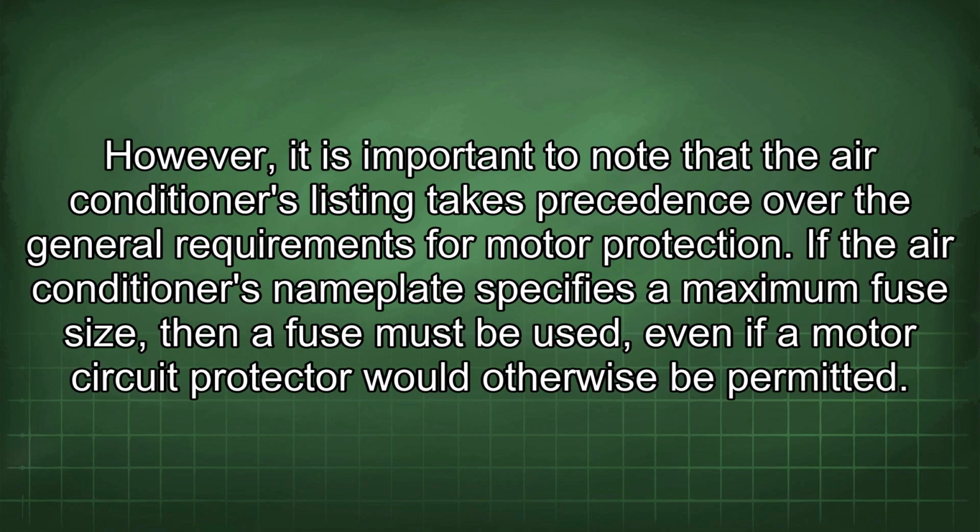unnecessarily. However, it is important to note that the air conditioner's listing takes precedence over the general requirements for motor protection. If the air conditioner's nameplate specifies a maximum fuse size, then a fuse must be used, even if a motor circuit protector would otherwise be permitted.